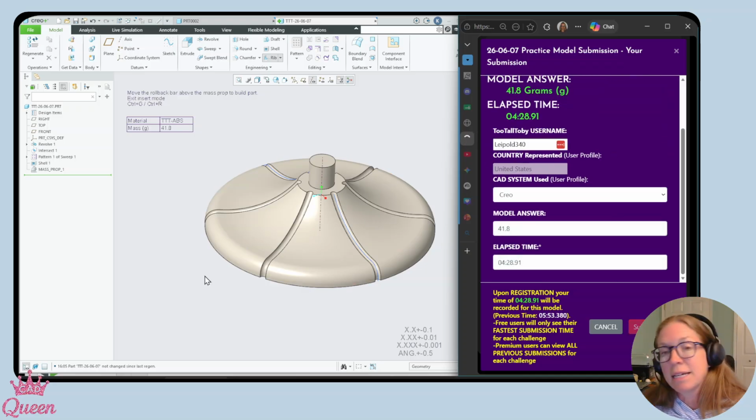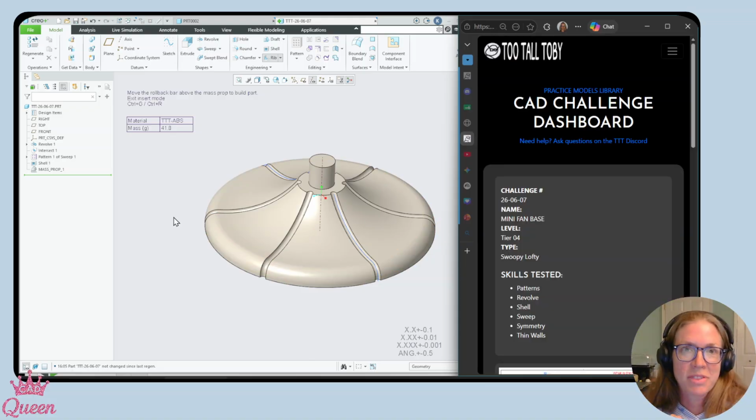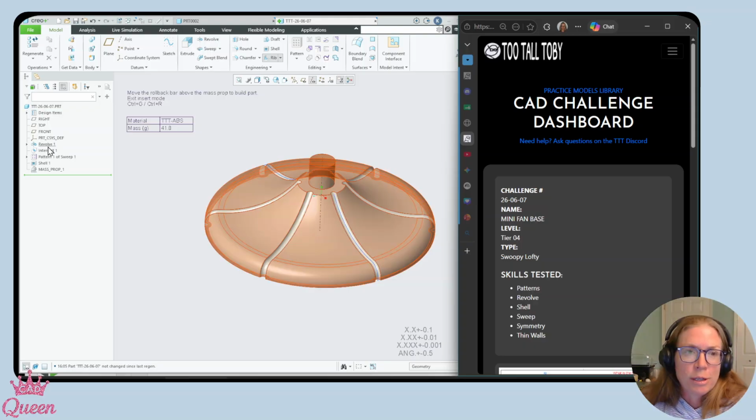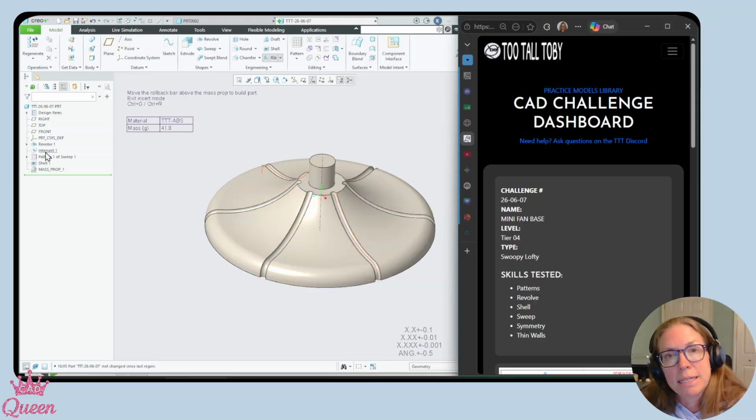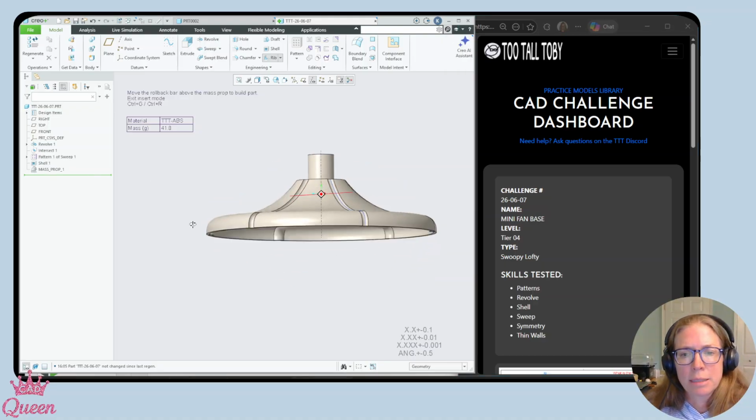For something that looks kind of complicated, in Creo, there's a lot of quirky things that make it a little bit easier. That is one of the things about Creo, that sometimes the easy stuff can be harder, but sometimes this harder kind of stuff can be easy. So building your sketch directly in the Revolve gives you all your diameters. The Intersect made it nice and easy. Just make sure you're holding down Control to get all those surfaces. For the Axial Pattern, make sure you turn on the axis and then do the angular extent, and then just add a shell with the bottom open.